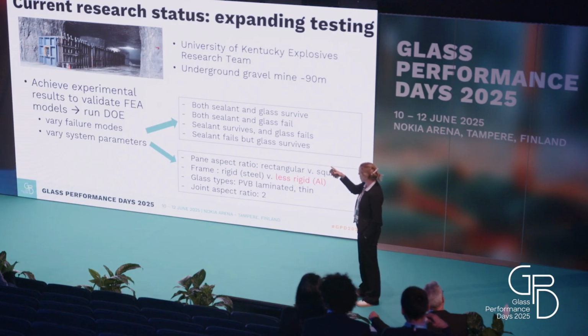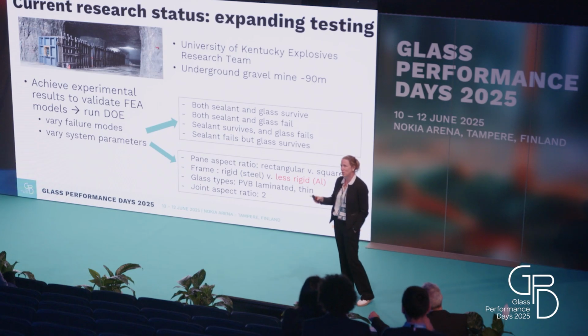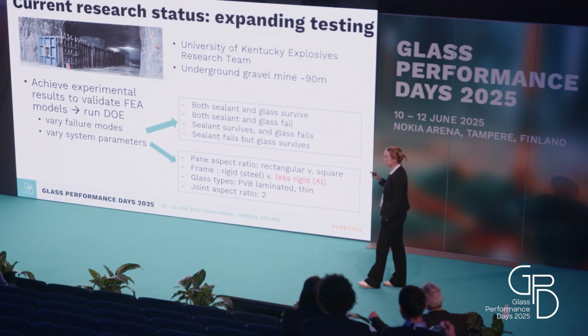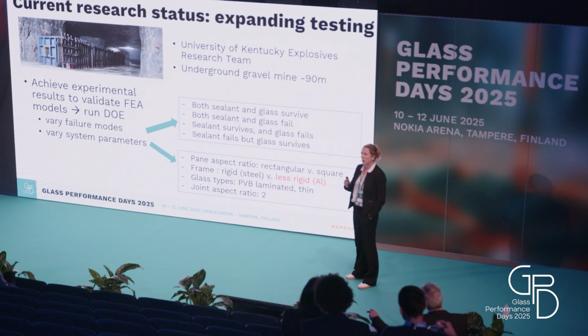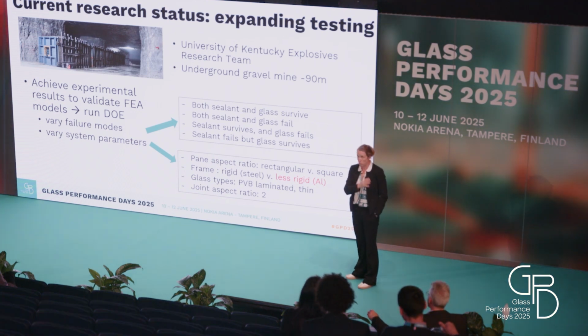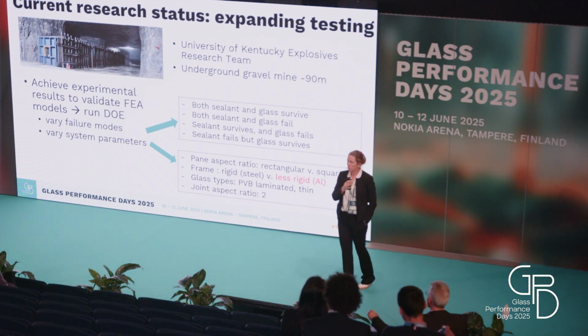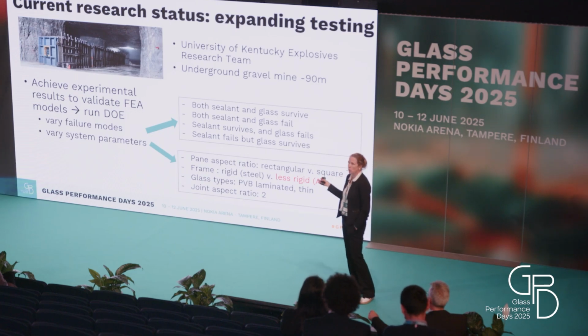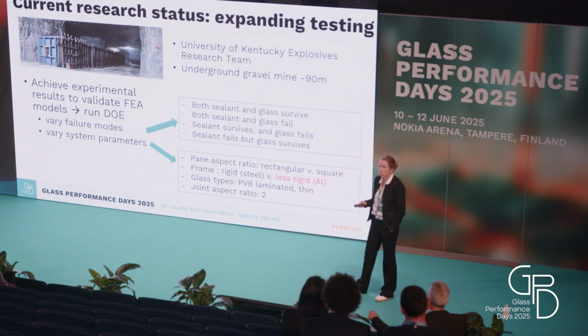And we have really developed a testing protocol with the goal of breaking stuff. We wanted different failure patterns. We wanted to break both the glass and the splice, but not the silicone. We wanted to break only the silicone. We wanted to break both of them, and we also wanted a situation where we broke nothing.